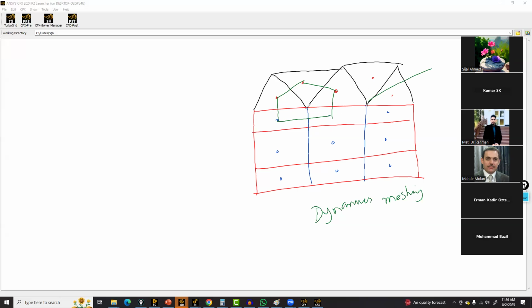So that's also the reason that the CFX results are more accurate, because it is using the high order elements. And thirdly, it has more convergence speed because it uses fewer elements. Now it creates, from five elements, only one element. So for mesh size, although you are giving maybe 5 million, the mesh that will be used by the CFX may be around 1.1 to 1.5 million. Okay, that's why, generally speaking, it's faster than the Fluent.